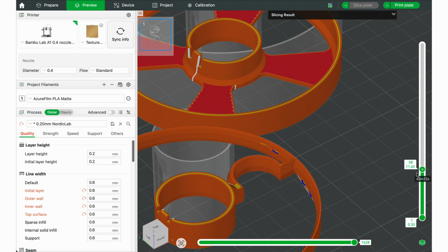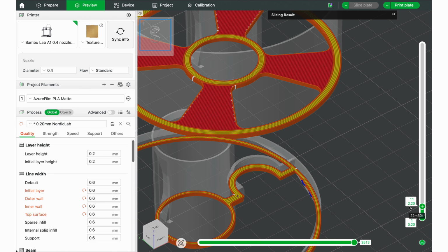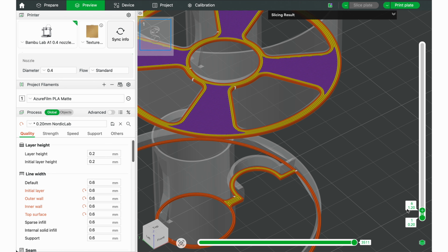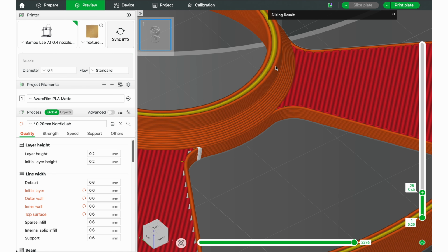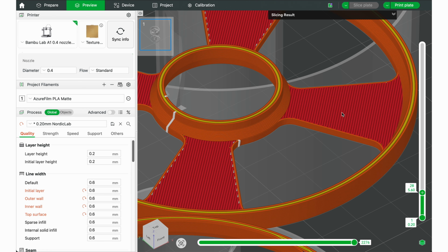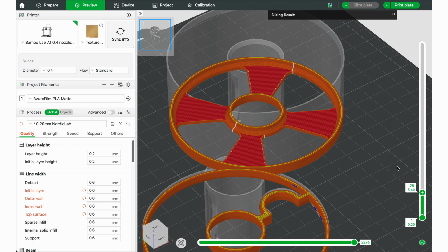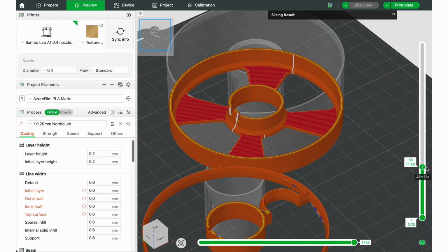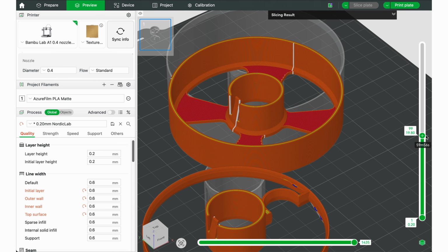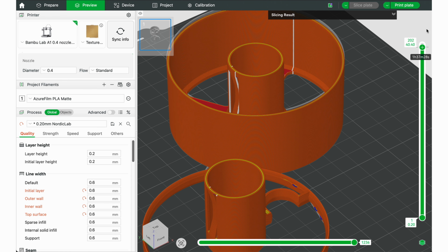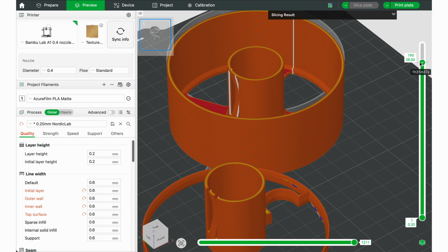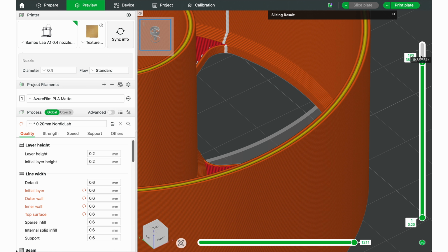And as you can see here, if I roll it down for both of the parts, I don't really have the infill. So I have only walls, and the walls will go from the bottom to the top, and these portions of the print will support the strength. You can also add the ribbon here, but it's really not necessary. If it's not necessary, it will save time with the printing if you don't have it, and also save the filament.